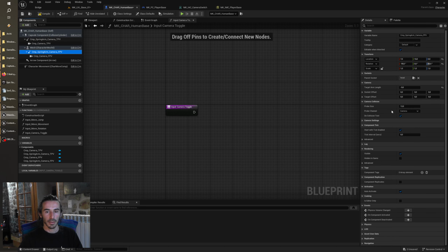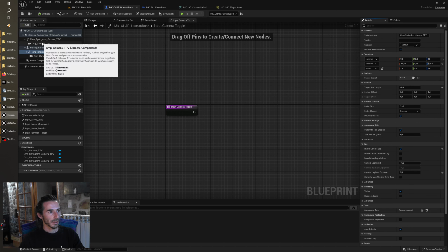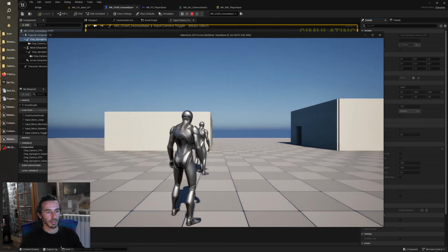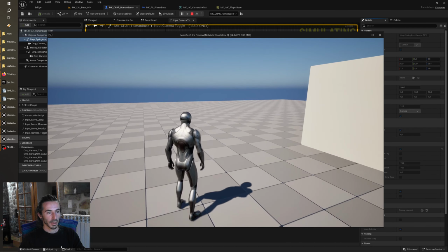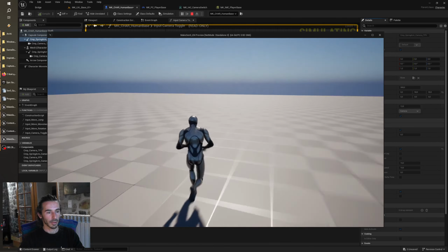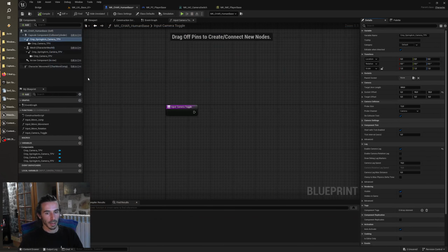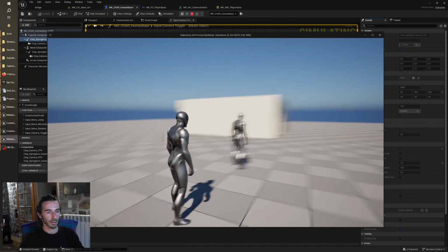This is something we have in the first-person view, if you followed my previous tutorial. It's the lag, allowing a smoother movement. And we can enable the lag. Let's just try with the default value. You can see now the camera takes a certain time to go to its supposed location. And if we decrease this a lot, we will see in action what is going on.